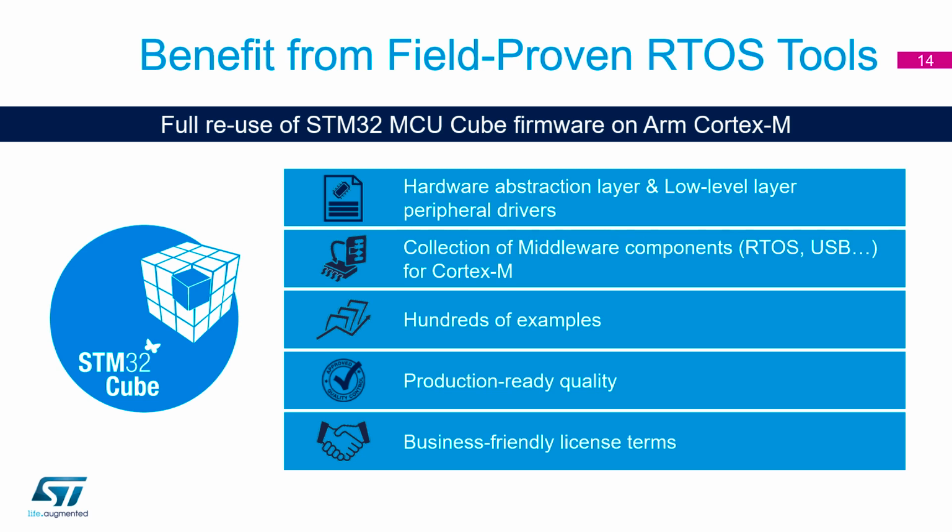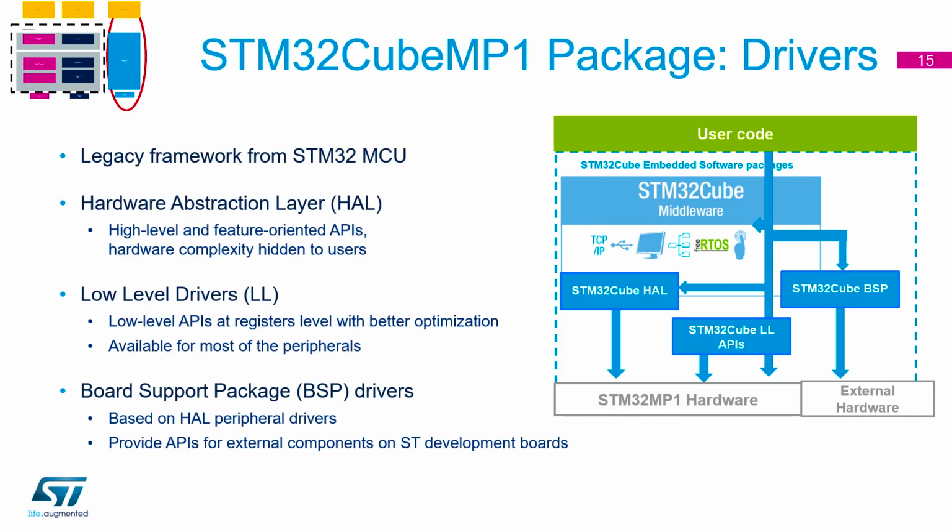So you don't have to worry about any of the licenses and reusing any of that code as a starting point for part of your application. So if we look at what you get within the Cortex-M world, you've got your legacy framework from all STM32 devices. You have the HAL or the low layer APIs talking directly to the hardware. You have those middleware components I mentioned, so lightweight IP, FreeRTOS, communicating either to the HAL or those low layer drivers.